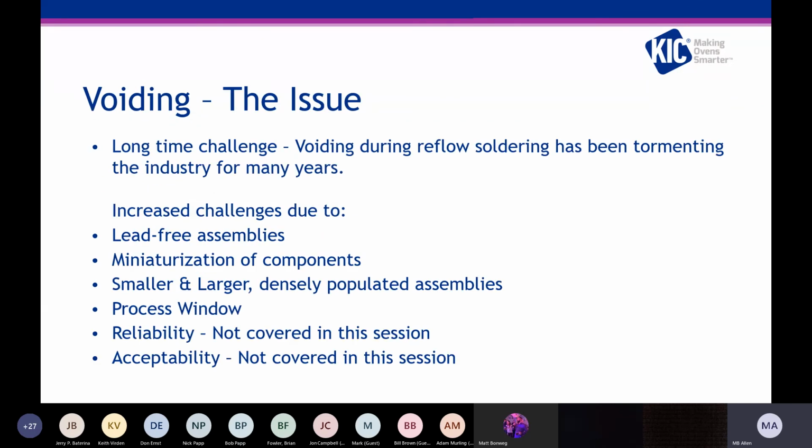So as you've heard, voiding is a long time problem. We've seen this in the past. But we're seeing it more now, and as you heard referenced, we're seeing it particularly on QFNs, LEDs, and other types of BTC components.